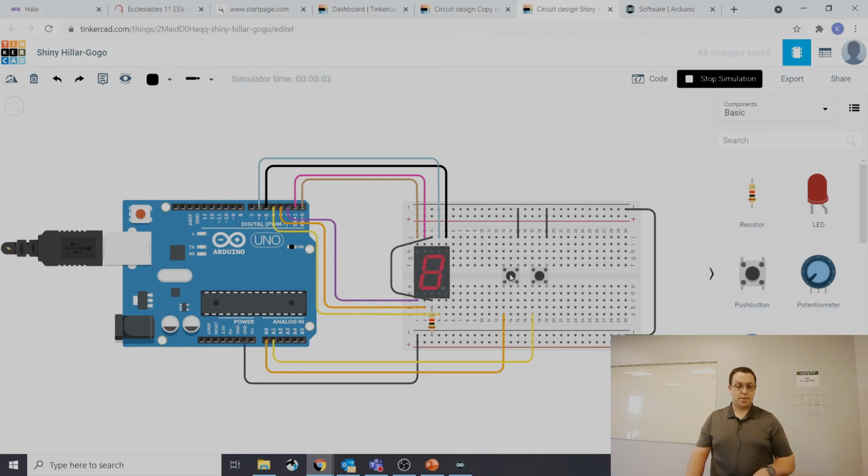I have them hooked up in reverse of what the other one did, but as long as it's going to the same analog pins, you'll figure it out. You'll get some numbers like this. The problem with the code is there's still an initialization issue in one of them where you have an extra piece: this display element F is being told to turn on all the time. So F and this center bar are running all the time.